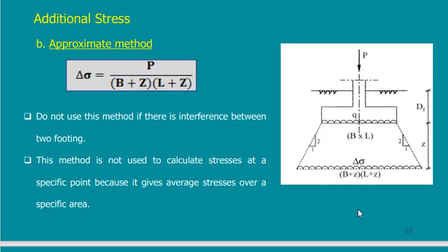The second method, we said that I have, say, a footing, and I want to calculate the stress at this point. To calculate the stress, it's not only at a point, it's a layer, it's a level. If I want to calculate the stress here, then I will take the same load, divide it by the new area at the bottom, and this new area, how I can calculate it, I will just use a sloping line here with an angle 2 to 1 to reach this bottom.